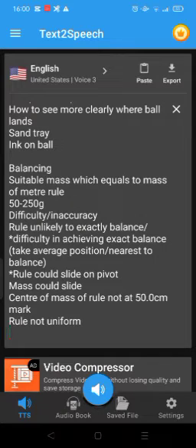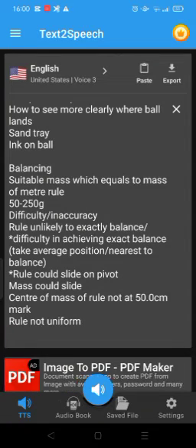How to obtain a more reliable value for the average circumference of a cup: measurement of circumference halfway up, top and bottom. More than one revolution used for the measurement in at least one position, and divide.